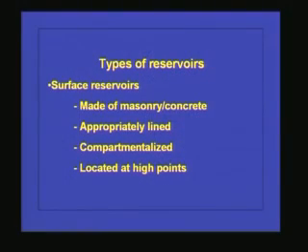Now there are two types of reservoirs, surface reservoirs and elevated reservoirs. The surface reservoirs are typically made of masonry or concrete, but when you construct these surface reservoirs, you have to line them so that there is no leakage from the surface reservoir. So appropriate liners should be used for this purpose.